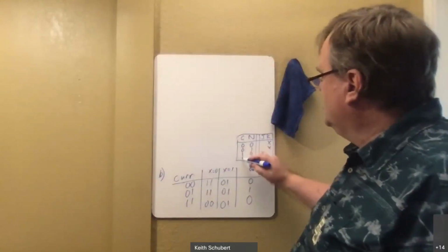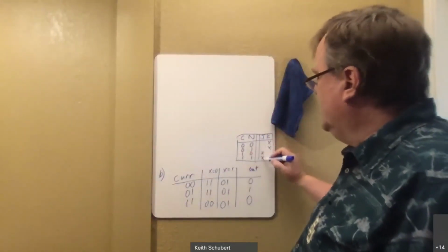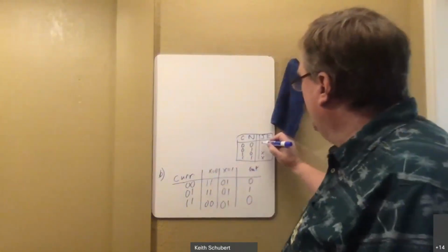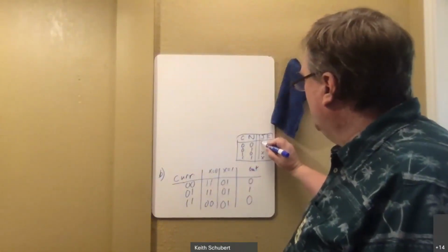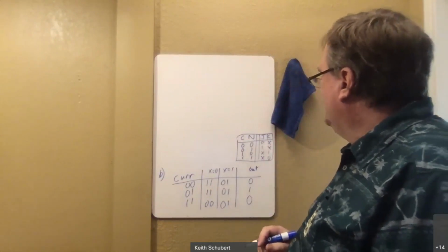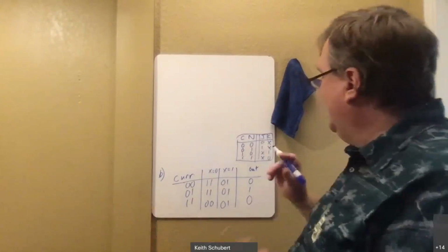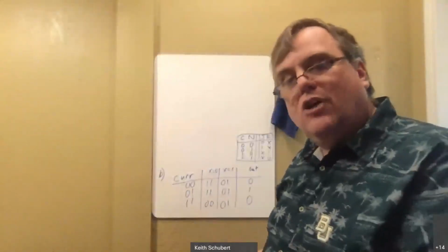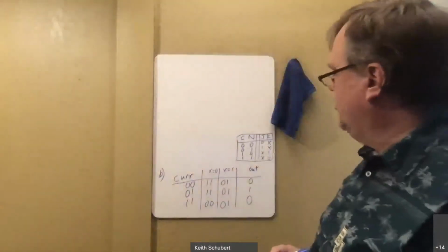When the current state starts at a 1, J doesn't matter. Right? You can deal with that. And then the remaining ones follow an XOR: 0, 1, 1, 0. So even though I can't read that table over there, I know this is the pattern, and that's how I remember it. So if you're ever stuck without it, that's the easy way to get it.